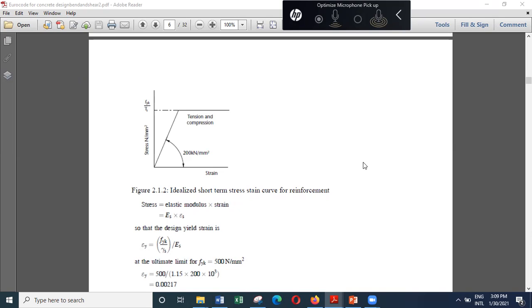And there's an advantage of this, because the inner portion of the bar is at a lower strength, it has a better ductility. So when you bend the bars, these bars generally tend to be reasonably okay because the ductility of the bar would be higher. So this is the hot roll process that is used, and they call it QT bars or QST bars.